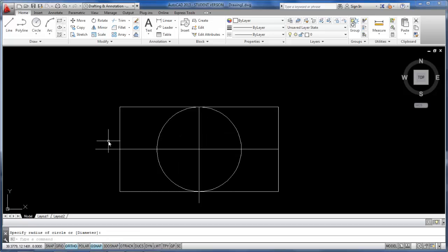Now I'm going to create 2 more polylines. I'm sure there's easier ways we could do this. This kind of explains and gets you used to some of these Osnaps. I'm going to click up here, enter. Enter again to give my command back. Click on the intersection there, and I'm going to take this one down. And then escape. My goal here is to create a square box.